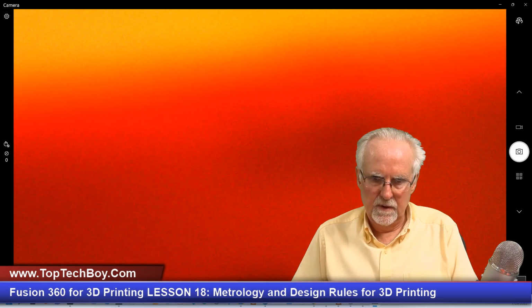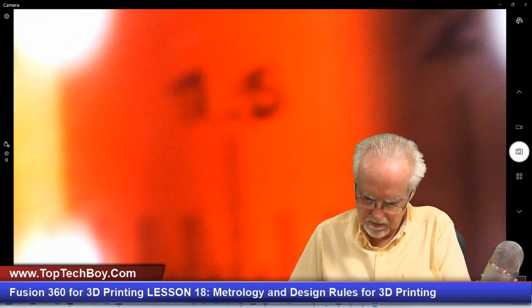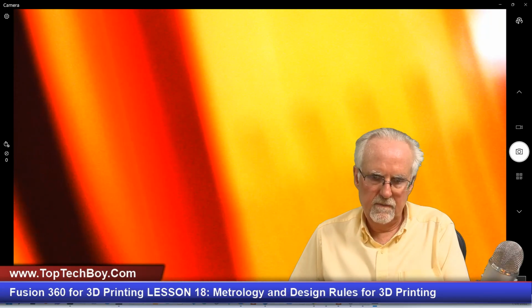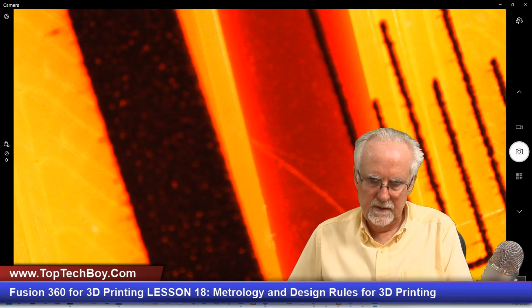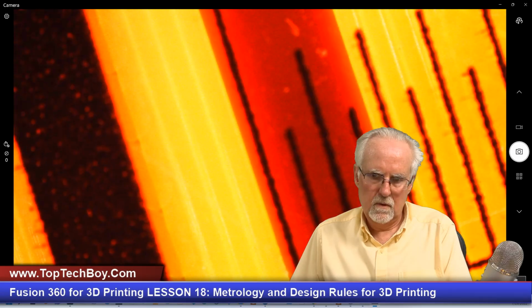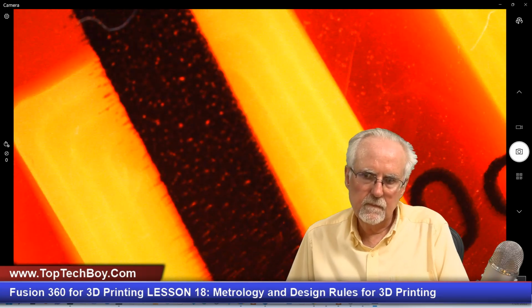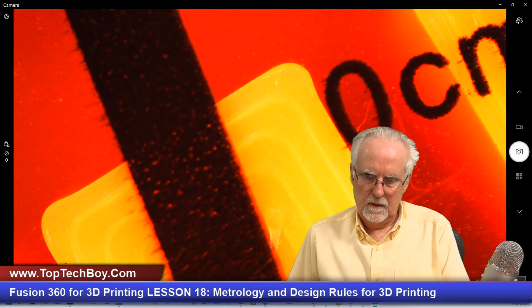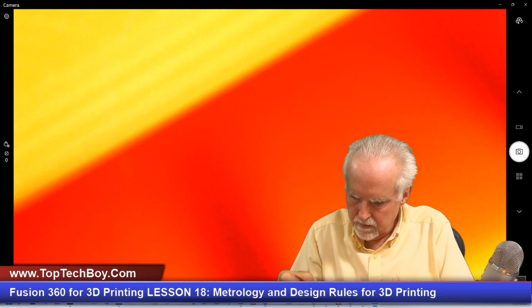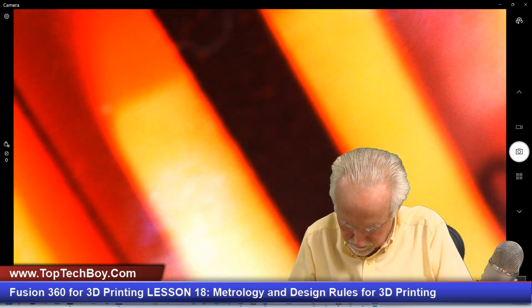And let me go down to my lower. Okay, let me see if I can get some focus here. It's like I need one more hand to really do this well. Okay, let me see if I can look at this. I'm having trouble seeing. Okay, so it's 0.5. So every 2 marks is 1/10 of a millimeter.